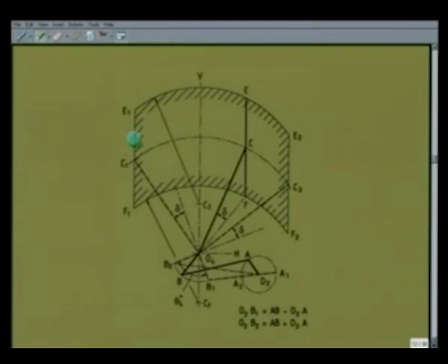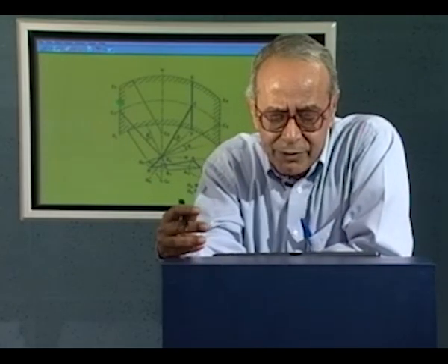So, as a designer, maybe we can make a very little change to make this field of wiping symmetrical about this vertical line. So, the second part of the problem is: retaining all other link parameters the same, change only the angle delta, which was given as 16 degrees, to make the field of wiping symmetrical about the line O4V.